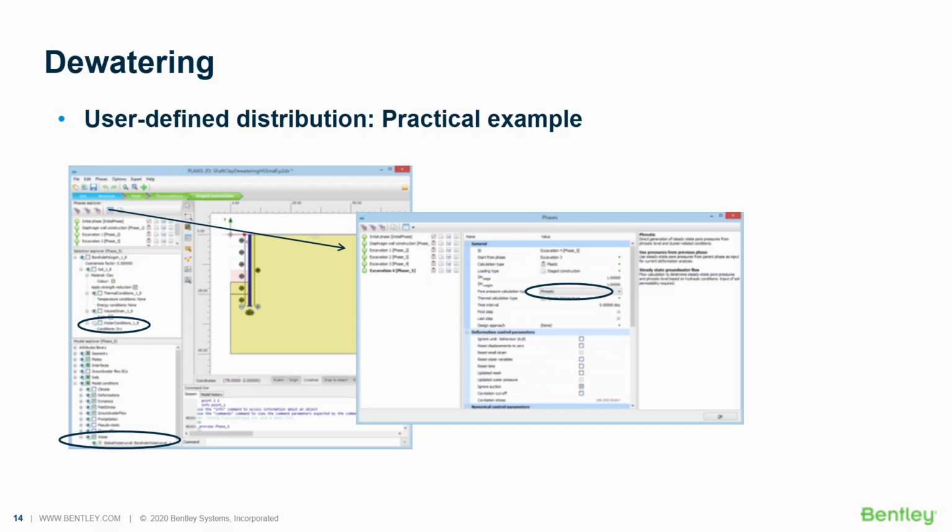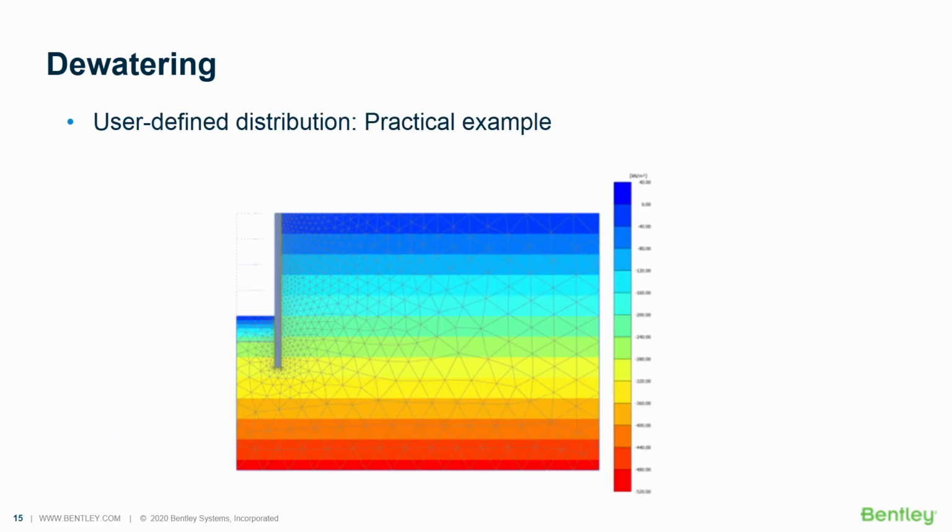And then finally, the last important model parameter you should take a look into is the global water level in the model conditions water feature here. And this could be by default set to the borehole water level, but you could also refer that global water level to any user-defined water level, as I will also explain later on. So this is what you would need for the first case. And this is also what I will demonstrate in the upcoming demonstration.